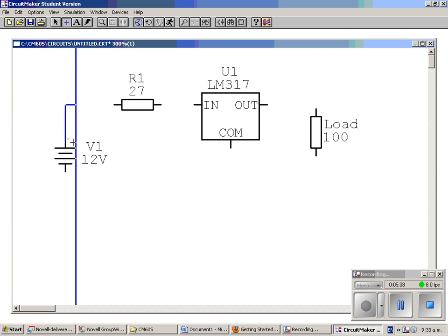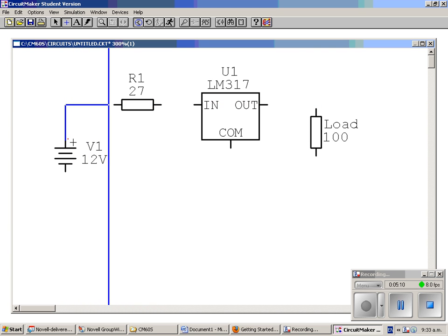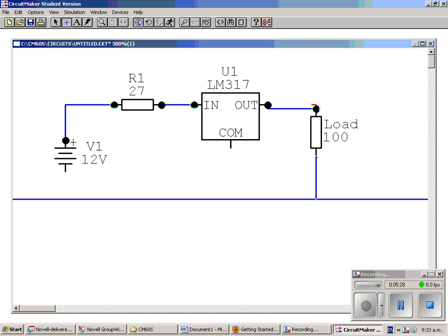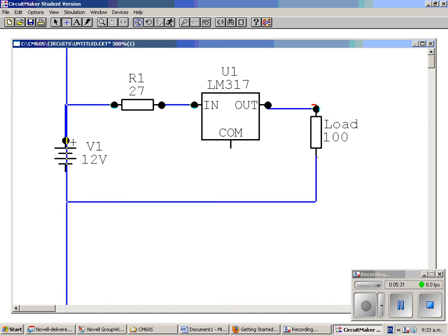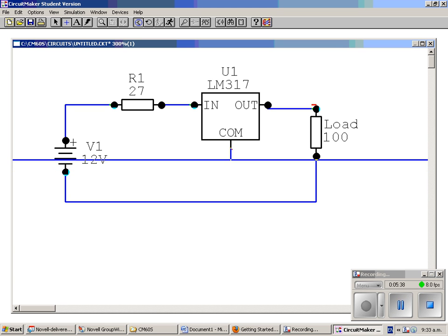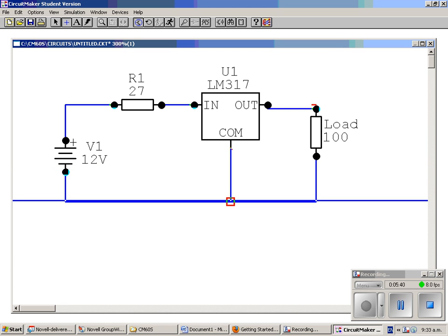So when I've lined it up there, I'll just give it one quick click of the left key of my mouse and it changes to a horizontal line with a vertical alignment line, so I know where to stop. Click on there and it drops the wire in. Two dots tell me it's found the connections. So left click, left click, left click, left click, one more, and here. And I don't need to actually terminate at a component. I can terminate on a wire if I want to, like that.